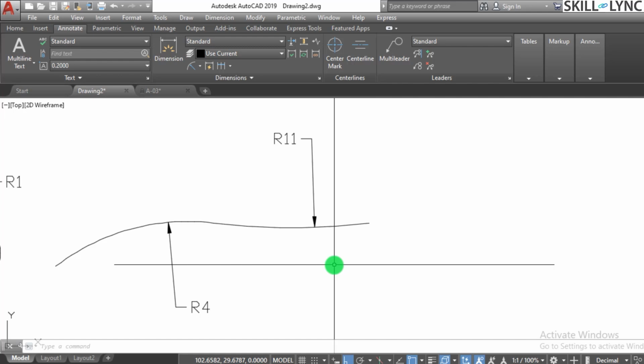You cannot use a diameter in that case, because the diameter is basically used when you're doing a puncture or a cut, when you're doing an opening, right? Whether it is the diameter of a bolt or a nut or a screw or something, in an assembly, you can put the diameter. But when you are doing surfaces, when you are doing profiling, if you want to go with radius or diameter, preferably you should go with the radius when you're doing profiling.